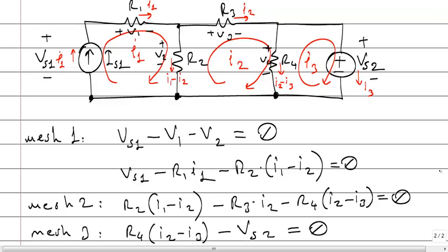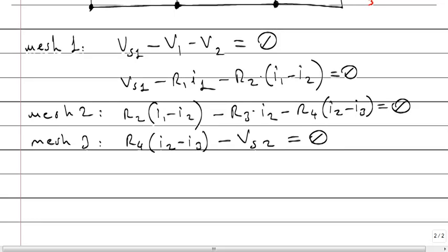Look, there is a current source here. Its value is given, I source 1. Capital I source 1. It is given. What's the current of this source in terms of mesh currents? Can you say me? Small I1, isn't it? So actually in this circuit, small I1 is very obvious.